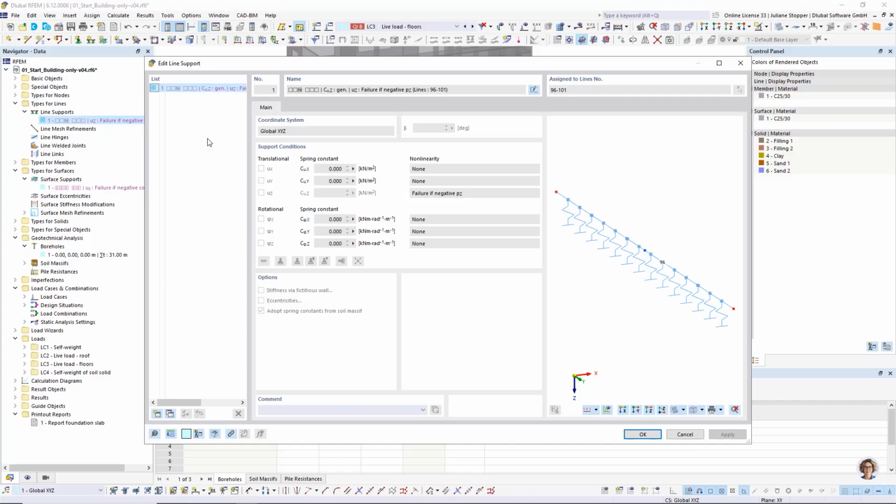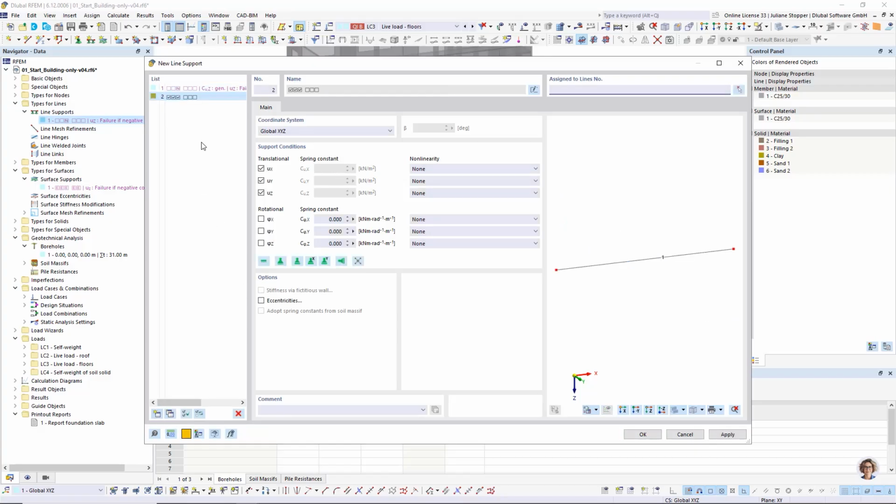Okay, we have a small workaround in the current state. If you just want to have the advanced half space method with just producing you the surface support, it is possible that you can here assign a manually defined support, for example this one, and give here a small value.